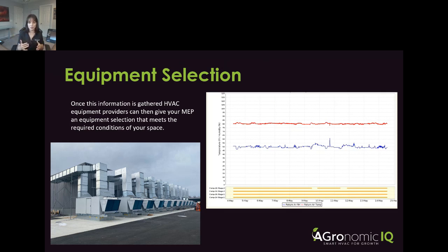And if you look down at the bottom, that's where the compressors are running. These compressors are running comfortably. There's a little bit of intermittent turning off and on, so there's a little bit of extra capacity, but this is perfect for this facility because going into the warmer seasons, this is spot on for what you want your environmental control graph to look like for how your facility is running.